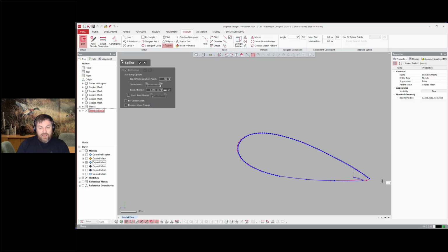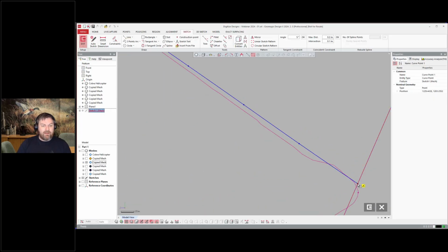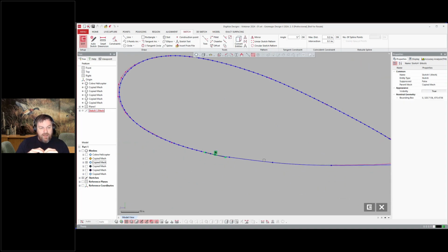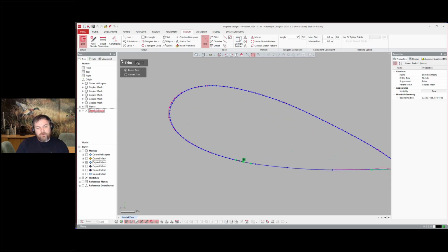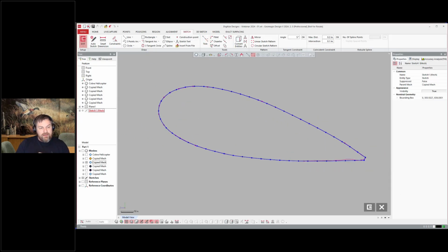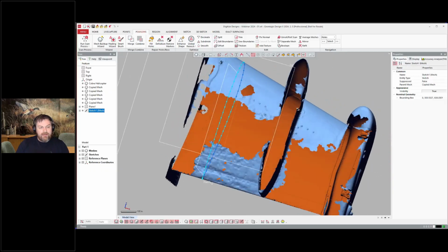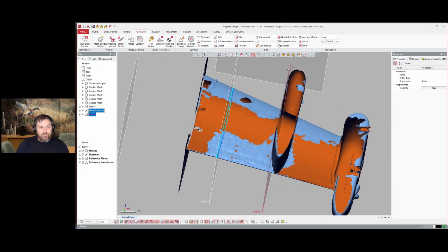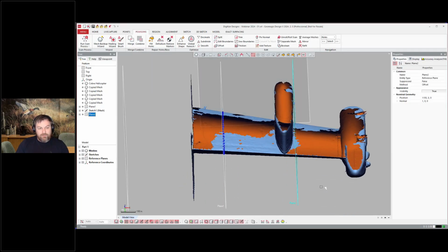And then here in this instance, I'm actually selecting that mesh and just fitting a spline to it. And for areas where I may not have data, or maybe that is the area where the turret connects or whatever, I'm able to draw and CAD model directly over those areas on my own. And in this instance, what I'm showing is we can cut a cross section, and we have that section called a mesh sketch and draw wherever we want over top of it. And this is a key component of DesignX, being able to do that.